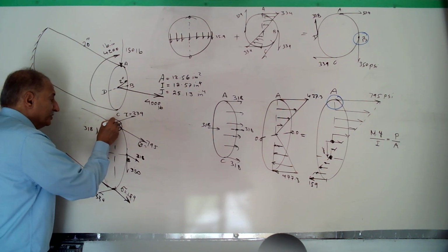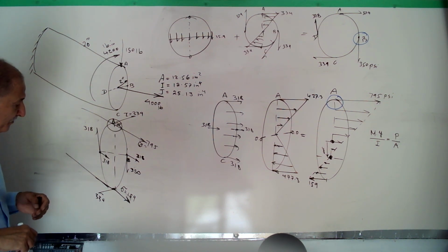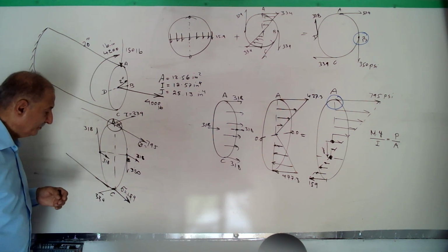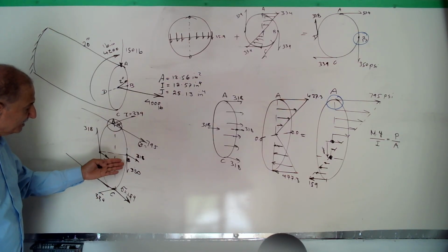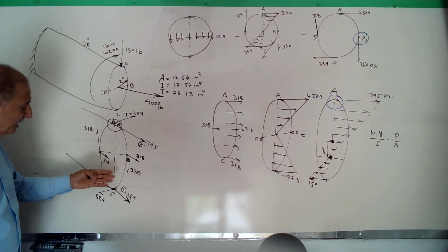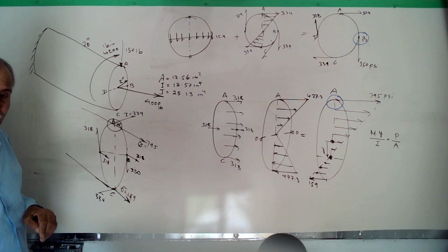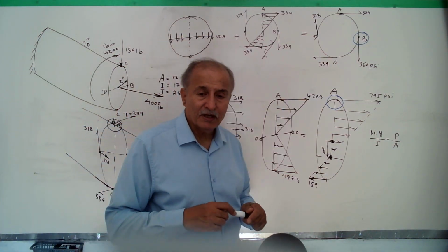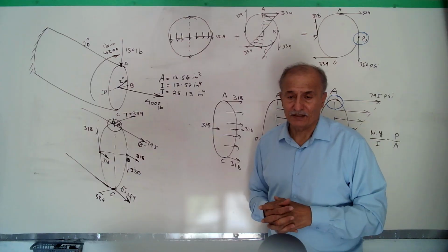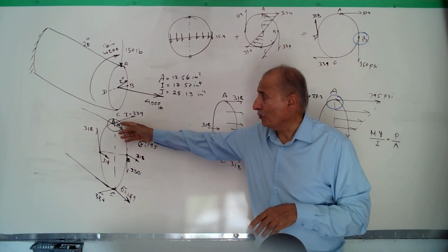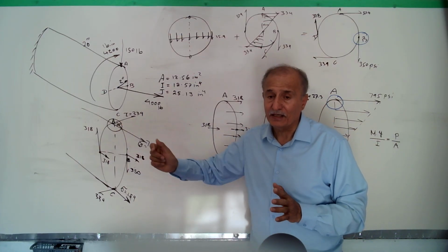One of them is this point A. This is point C. And also you will see that here tau shear is larger, but by a considerable amount normal stress is less. Then the critical point for this design is A.